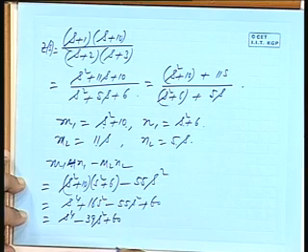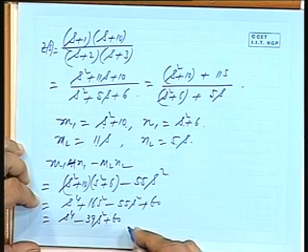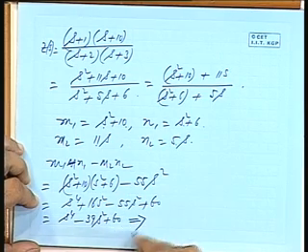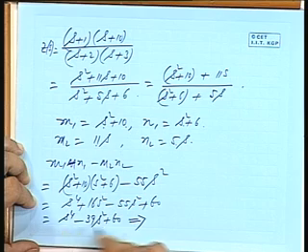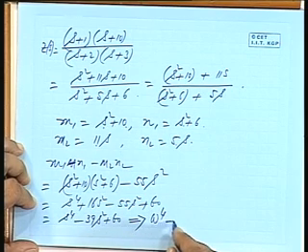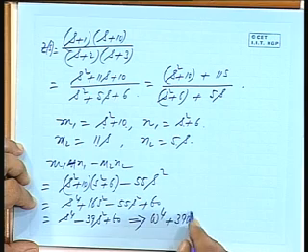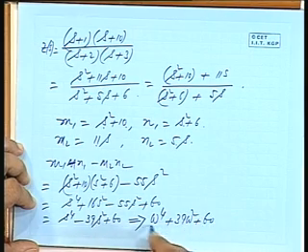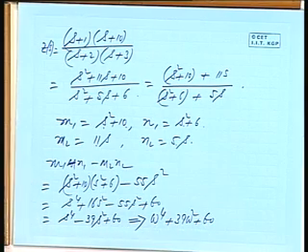plus 60. Now, if you evaluate at s equal to j omega, what will this give you? If I evaluate this at s equal to j omega, omega to the power 4 plus 39 omega squared plus 60. Is it always positive for all values of omega? Yes. So it is realizable,